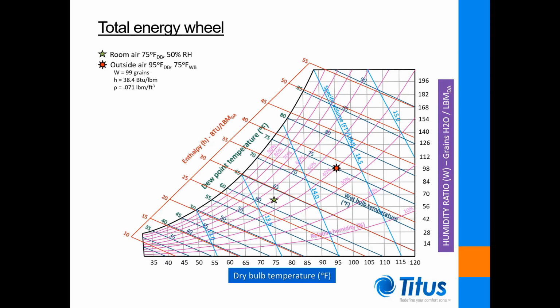This process is depicted on the psychrometric chart as the diagonal line associated with the label 1. The diagonal direction of the process line indicates that both sensible heat and moisture are being removed from the outdoor air as it passes through the rotating wheel. Conditions leaving the wheel now correspond to 84-degree dry bulb and 69-degree wet bulb temperatures.